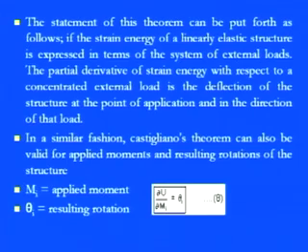So Castigliano says that even if you have a number of loads, you can simply differentiate the strain energy with respect to them, and they will give you the deflection at those points towards the application of the load. In a similar fashion, Castigliano's theorem is also valid for applied moments and the resulting rotations of the structure. He has given four or five theorems, but generally we restrict ourselves to those.